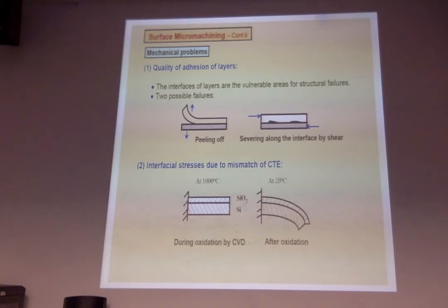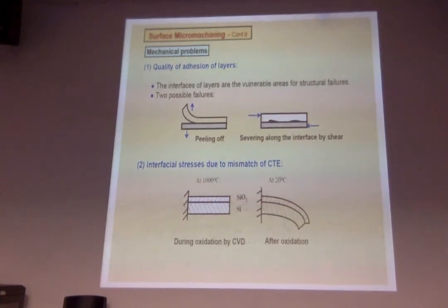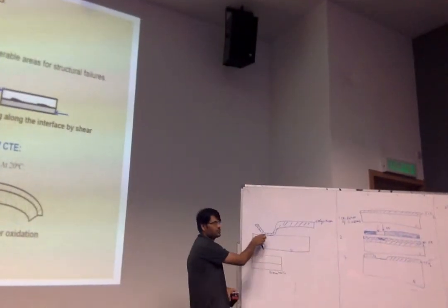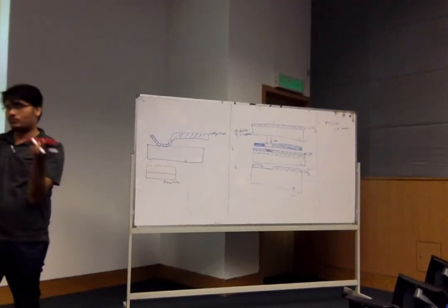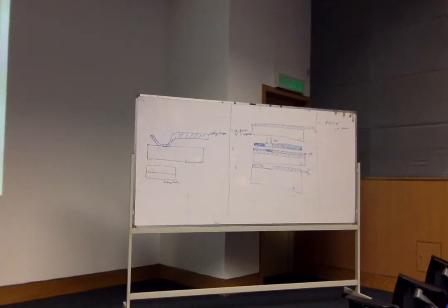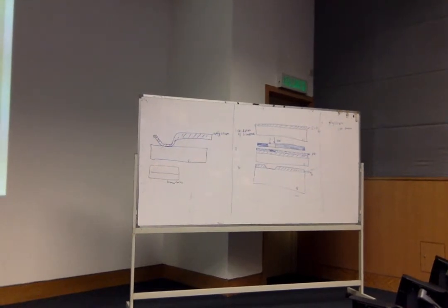Every material in this world will have its own coefficient of thermal expansion. So when you heat them, the expansion rate could be different for different materials. When you have 2 such bimetallic strips, one expands faster, the other expands slower. I said that one can achieve actuation in the actuator section, but the same thing can be a problem here. When you are heating them, they will actually have some bending. It can bend because of the thermal stresses. This is during heating up.